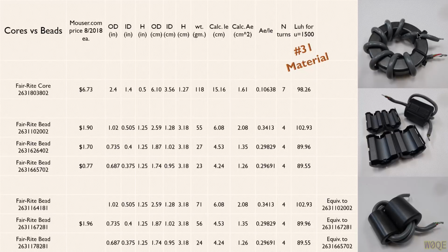And this can be wound in both a conventional manner like this, or it can be wound in a crossover manner, which I'll show later. But there's a certain number of turns here that will give you an optimal value. And you can also wind your wire through split toroids like these, or solid toroids like these. In this case, these would have to have a connector put on later. But nevertheless, let's just look at these very quickly.